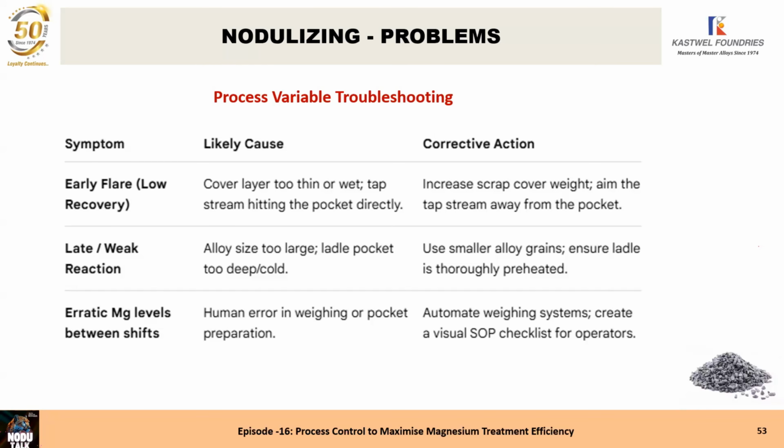In some of the old foundries, maybe 50 years back, people used to cover the ferrosilicon magnesium with resin bonded shell sand. When you did this, you could fill up the whole ladle without the magnesium reaction starting. And then when the full ladle amount of metal to be treated is delivered into the treatment ladle, you take an iron rod and puncture the steel cover shell, and the reaction starts. And the recovery is very, very high, close to 60%, 62%.